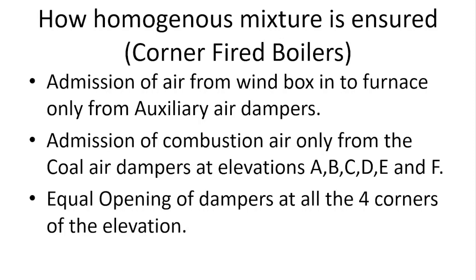How is a homogeneous mixture ensured in corner-fired boilers? Admission of air from the wind box into the furnace only from the auxiliary air dampers, then admission of combustion air only from the coal air dampers, and equal opening of dampers at all four corners of the elevation.